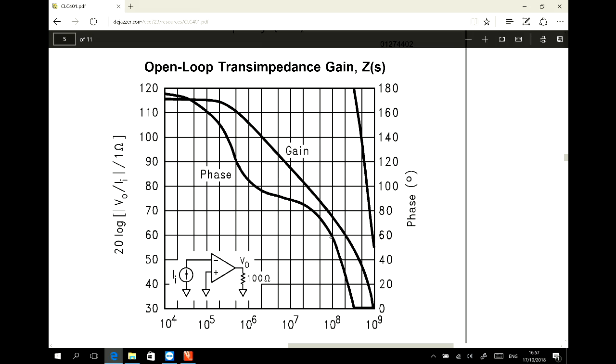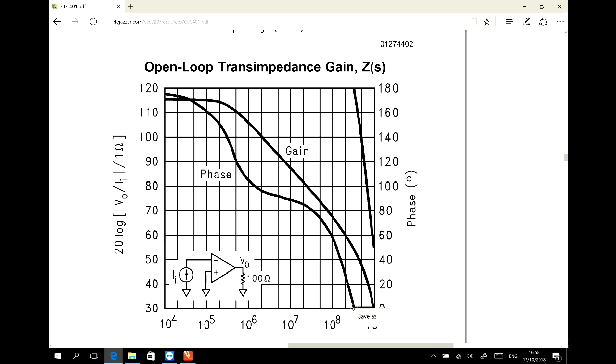So because of that, we say that, okay, 2.5K is a good number because it gives us a phase margin of 60 degree, and also the bandwidth is not that much reduced. If you go to higher bandwidths, I mean, for example, at this point, here, then you see that your phase margin is almost zero. And it means that if you design a system at this point, it is unstable. It's totally unstable.